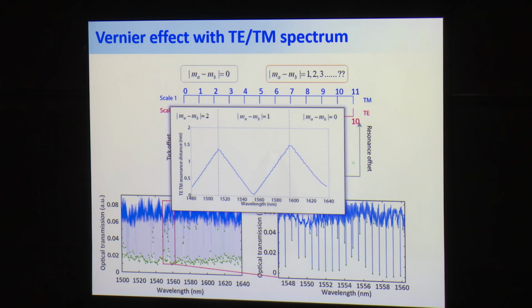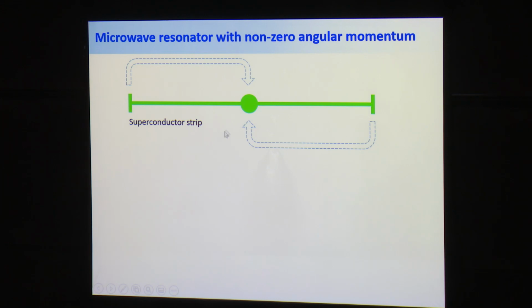So that gives you weaker anti-crossing, you work over here. Then you also need to engineer your microwave to provide that loss of angular momentum. So the way to do that, you take this lambda resonator. You make the center of your lambda resonator fatter and the edge also bigger. Then you fold it over.